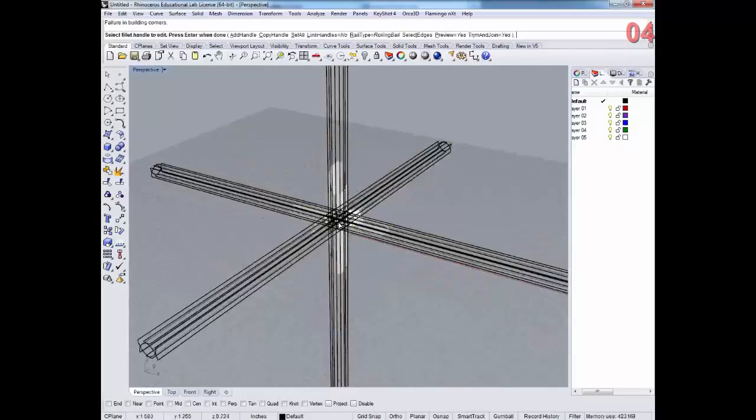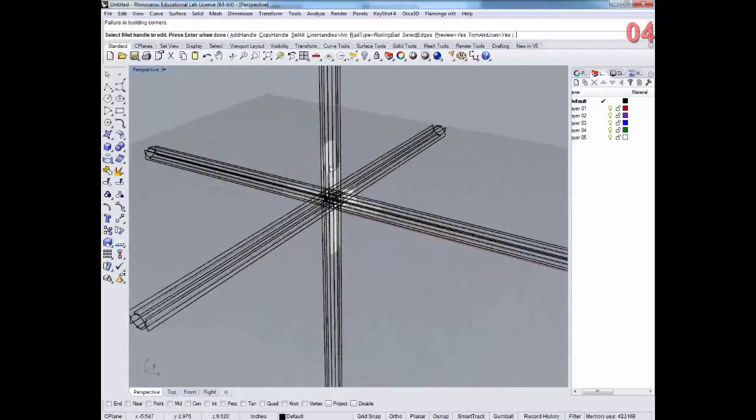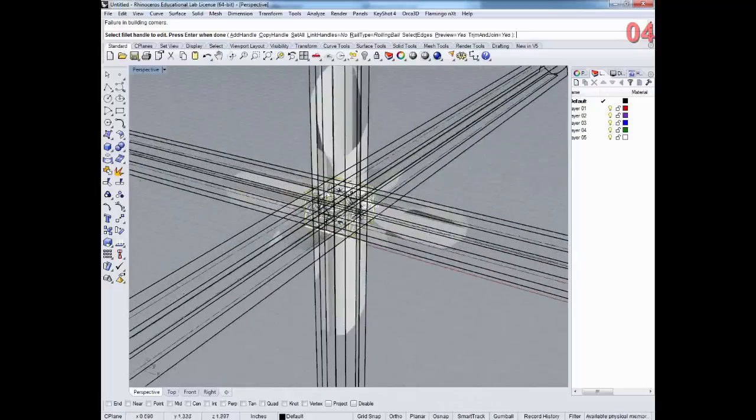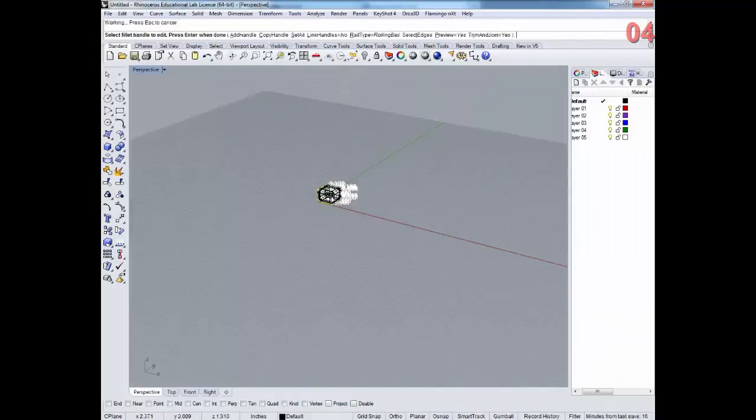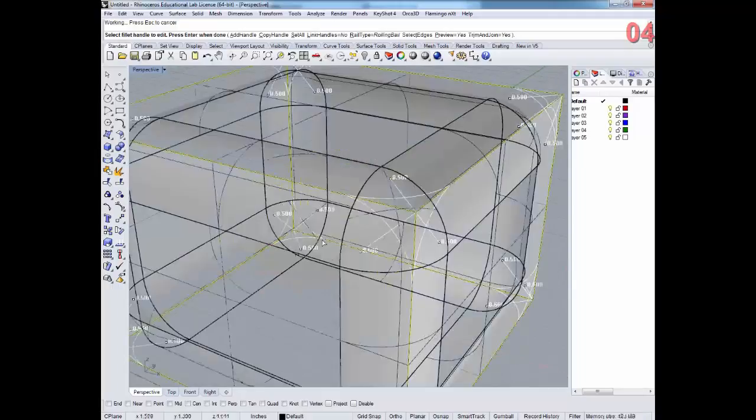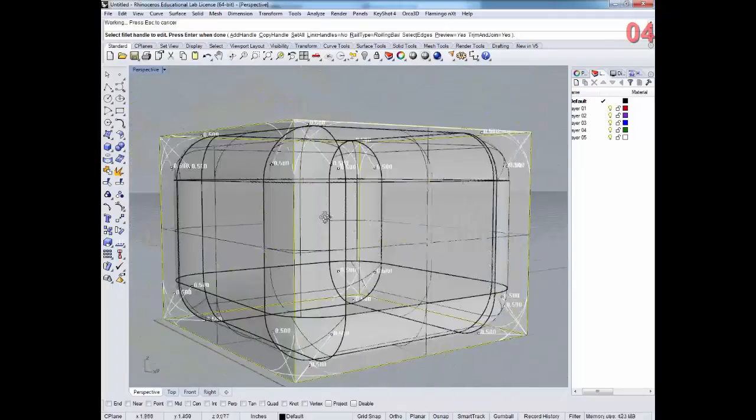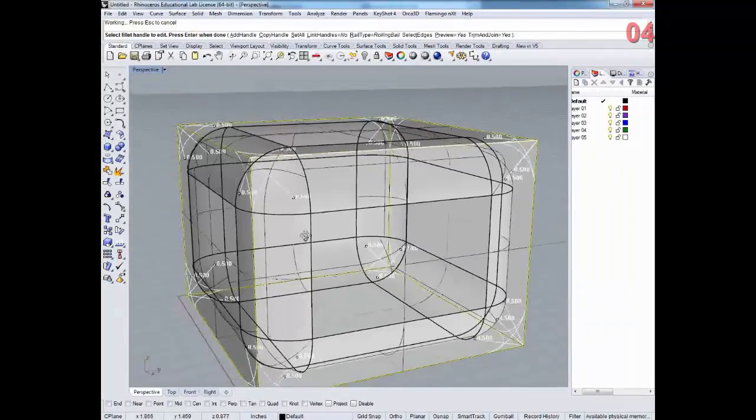When you get that, that means that your values are off in some way. And so I'm going to use my set all command, and I'm going to change that back to 0.5. And you notice that now when I change it to 0.5, I get a preview of a clean object.